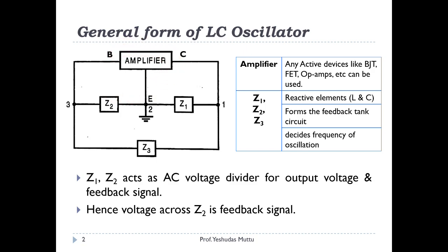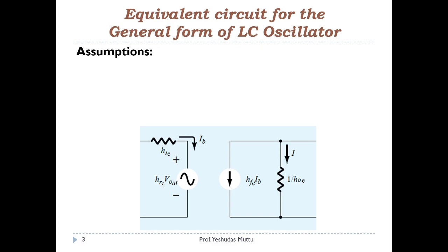What we had studied about the equivalent circuit in EDC1 were the re models and hybrid models. So what we are going to do over here is make use of the hybrid model. Let us have a look at this hybrid model. This is a complete hybrid model, if you can recollect from EDC1, wherein I have hie, hre Vout, hfe IB and 1 upon hoe.